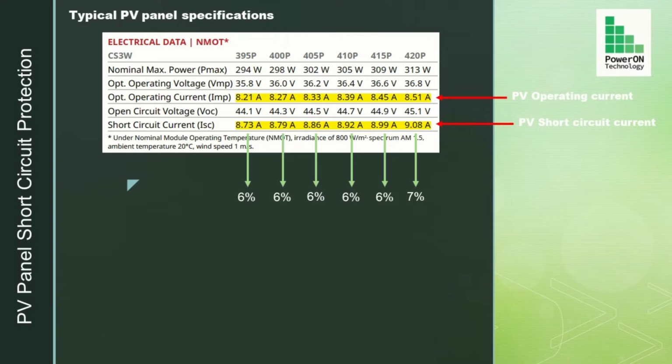Usually, the operating current and short circuit current in an electrical network differ by orders of magnitude. Take for example a typical single-phase household supply, where the operating current is 15 amps, and the short circuit current can range from 2500 amps and higher. Discriminating between normal operating conditions and a short circuit is rather simple in this case of a household circuit. Not so with PV panels.